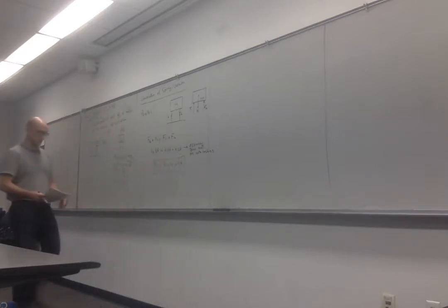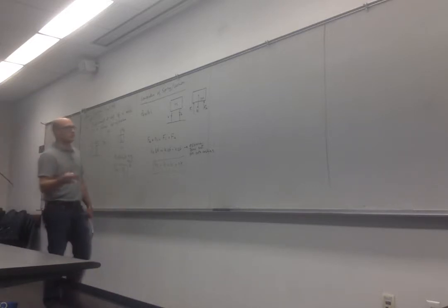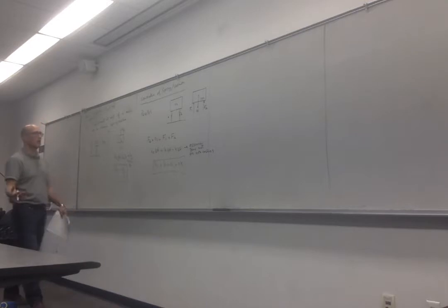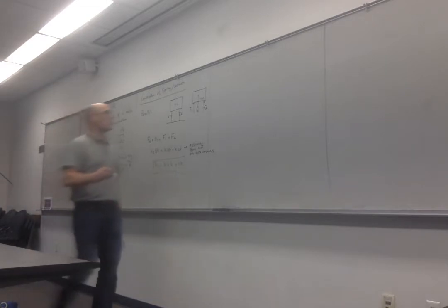So if you have cushion in parallel, you basically have to assume that the equivalent spring constant will be the sum of the K's for all of these cushions. Again, there's a lot of assumption here, and things are not always this way. So you may have to tweak this a little bit, but obviously this assumes that the mass of the product is uniformly distributed. If you have a product where the center of mass is more on one side than the other, you may have different deflection and so on. This is basic stuff, basic tools to start our analysis, and then you can go to more.